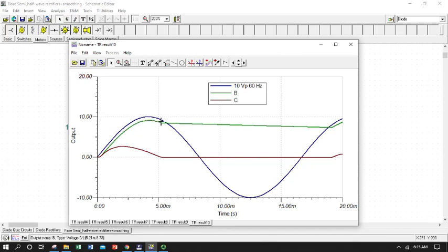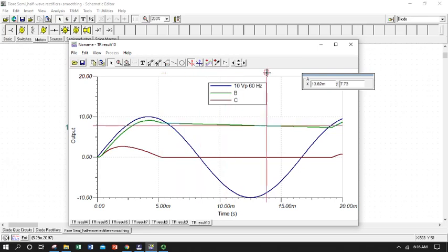And it rolled off a little bit, but at this point, we'll get our marker. At this point, the capacitor took over and supplied voltage to our load, and you can see it's decaying very slowly. So we've got a nice long time constant in our RC circuit. So we picked a good sized capacitor for our resistor, and we could redo our analysis, show the next cycle and how we're picking up just on the back end of the next forward cycle.